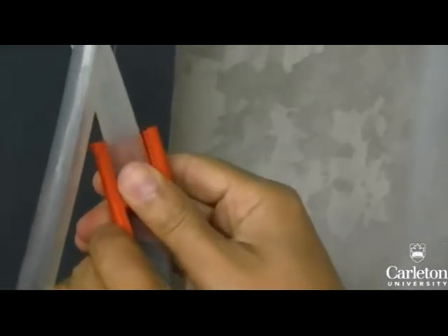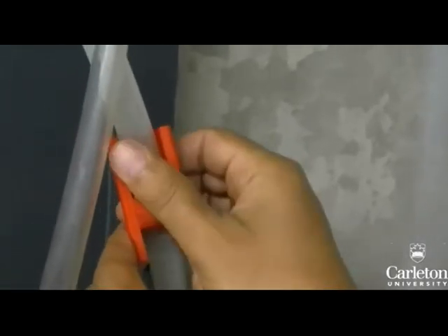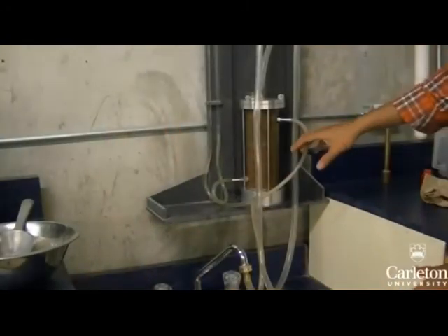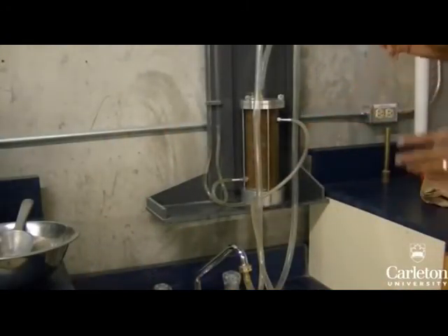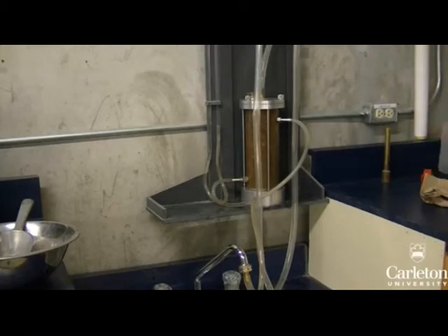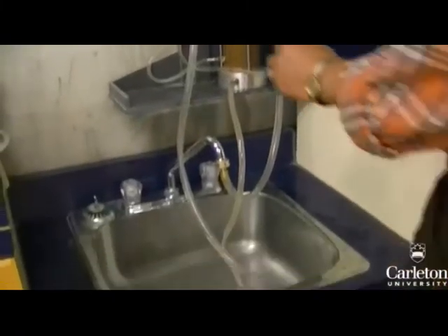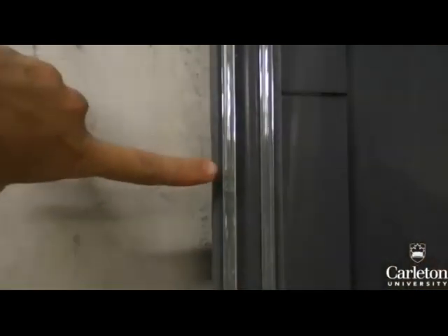Now open the valve to let water into the sample. Before we start measuring flow rate, we need to let water run through the sample. This is to remove any trapped air. Let the water run through the system for a few minutes. Here we can see the pore water pressure being recorded on the 2 manometers. Now we can start measuring water flow rate.